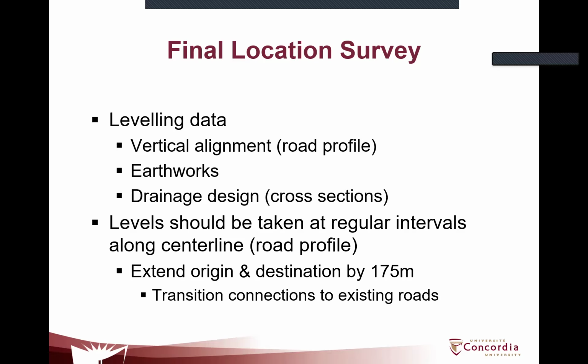You will use some leveling data as a next step to build up the vertical alignment. And then after having the vertical alignment, you superimpose the vertical alignment with the terrain. And that superimposition of the two lines will tell you the earthworks that you need to do.